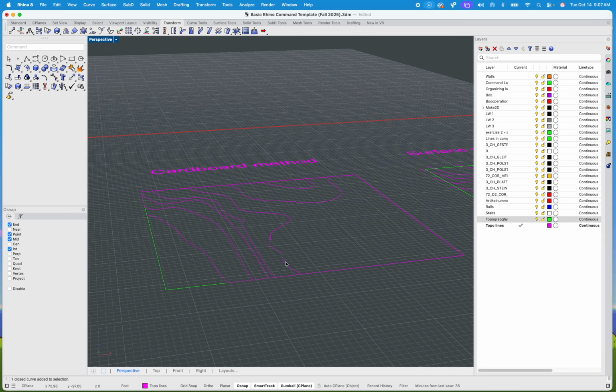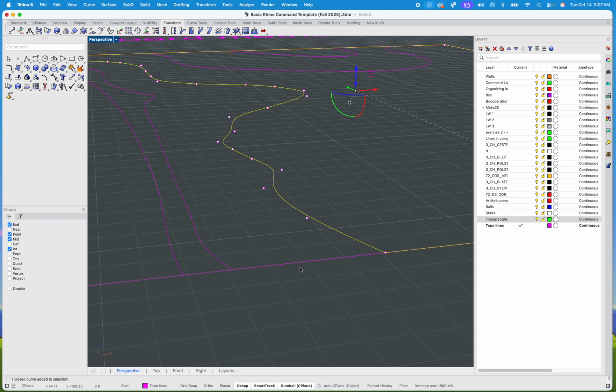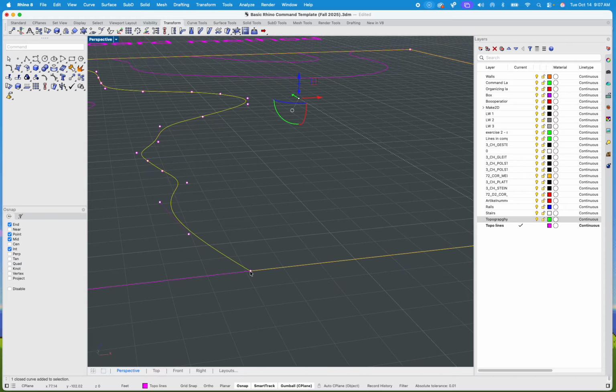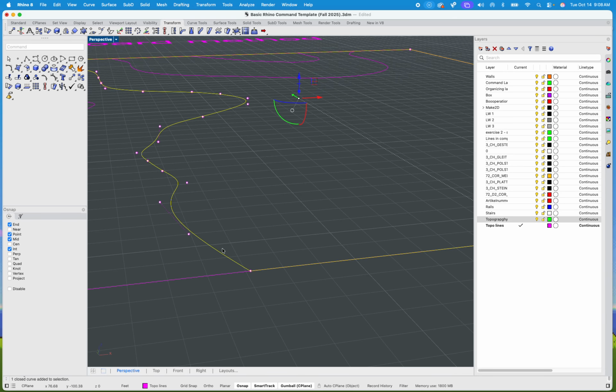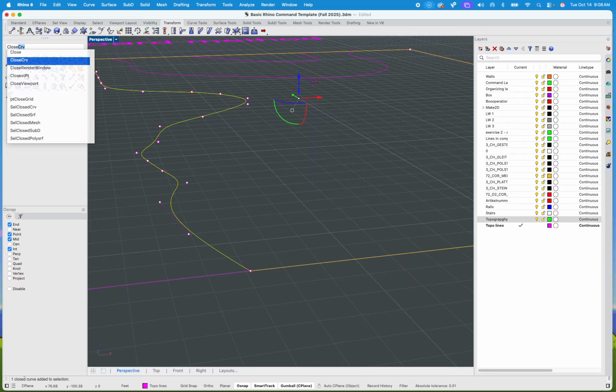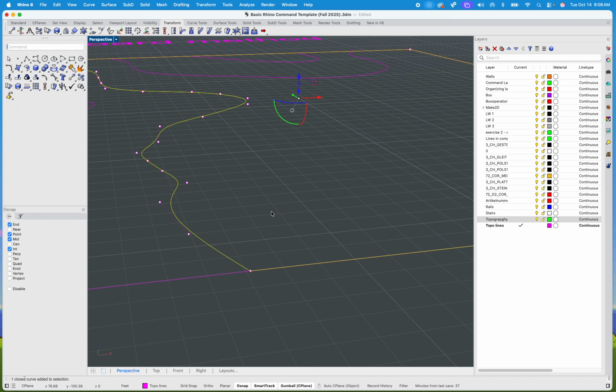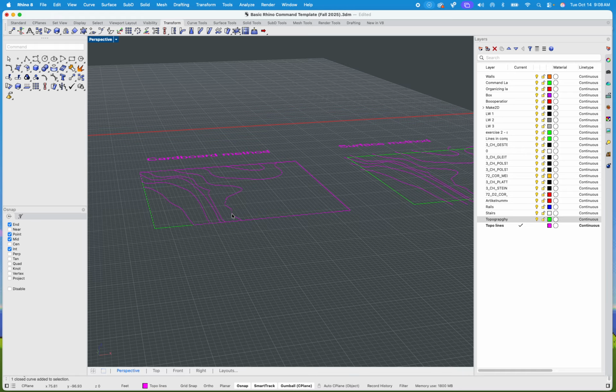So in our case, you can close curves. So what if that's accidentally open? What do I mean by this? Maybe I can take this point. Dang it, it's connected. Sometimes you accidentally have an open curve. What you can do is actually type close curve, and if it's accidentally open and you're extruding, I think we went over this actually in the stairs, but I've noticed it a lot in our students, guys. You guys are extruding stuff and you're noticing it's hollow still. That's usually because there's not a closed curve, right? So be very careful. But again, there's actually a command called close curve, and close it before you extrude it. Again, close it before you extrude it, right?